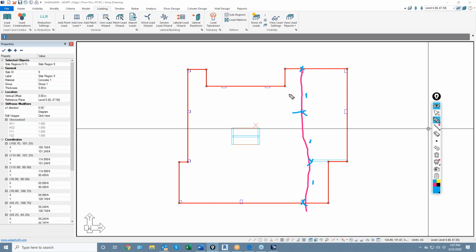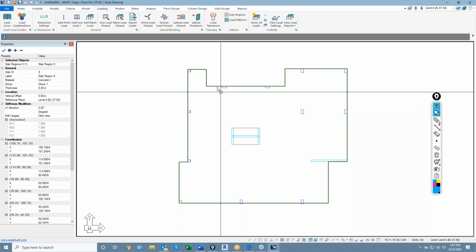And when you check that, it's going to give you a percentage here. Maybe it says 50%. And that 50% is a function of the self weight and the reserved dead load. So if you want the program to check load balancing based only on self weight and simply ignore the dead load, what you're going to want to do is disassociate any load from that reserved dead load case.